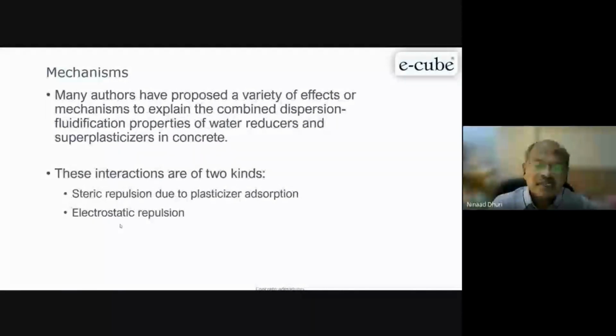Now, certain admixtures also contain a lot of polymers, so that also gives more strength in the concrete. Because some are pure water reducers, and some are a combination of polymer and water reduction capacity, you get more strength also.